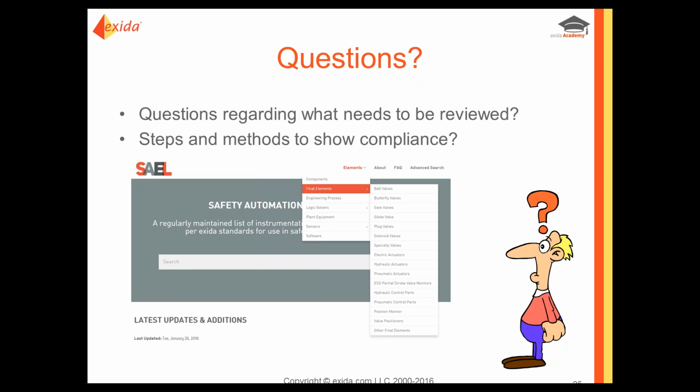However, for a SIL calculation or a SIL verification report, that's quite transparent. You could just provide the evidence to say, here's our evidence showing that this final element we've included considered everything. And that's more to the point that Exida is making, that you don't really need to certify every possible valve assembly scenario. You just need to demonstrate the process is robust. I'm not sure I've completely understood the question, but hopefully I've answered it.